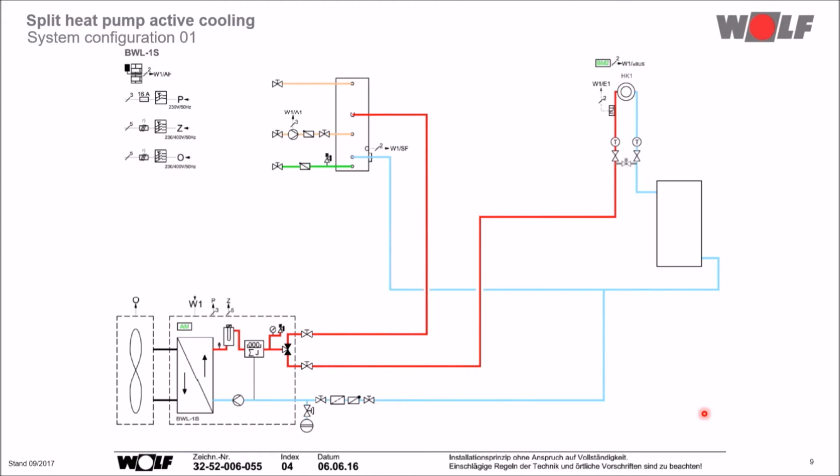In the factory setting, the cooling function is not available. When the cooling function gets manually activated and a buffer is connected as well, we recommend to bypass the buffer in the cooling mode with a 3-way converter valve. If this isn't done, you will get a higher energy consumption and the buffer needs to be diffusion insulated.